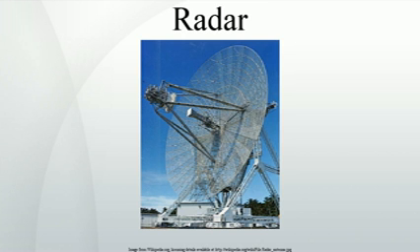Another technique uses a moving target indicator that subtracts the received signal from two successive pulses using phase to reduce signals from slow-moving objects. This can be adapted for systems that lack a coherent transmitter, such as time-domain pulse amplitude radar.